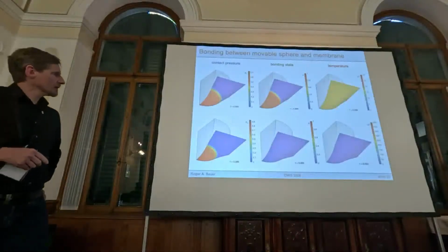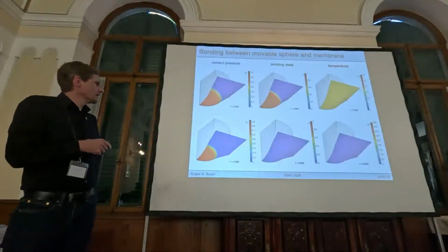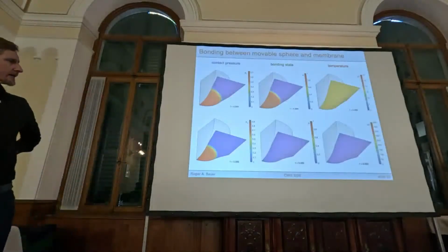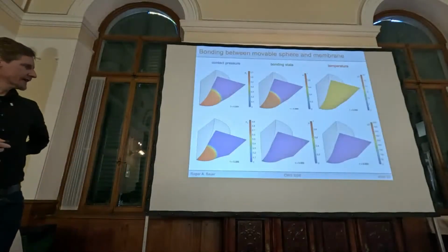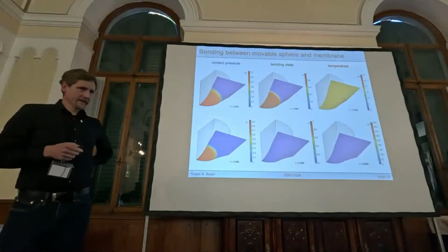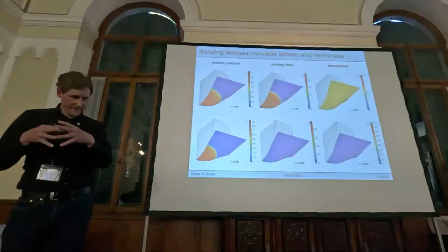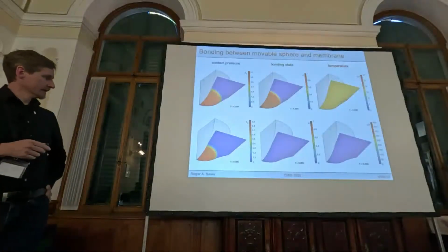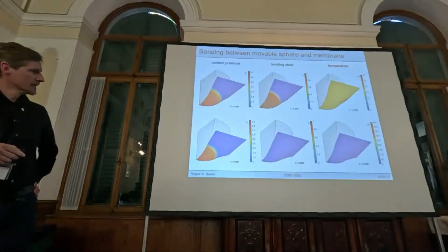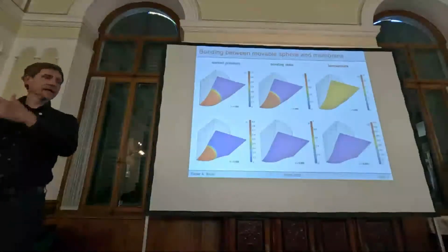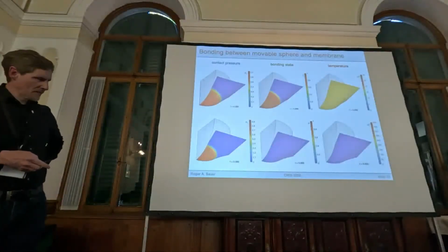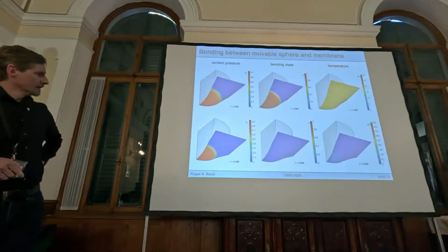As a toy problem, I also looked at the other way around. You can also make the ball come up if you examine the Gough-Joule effect, where the stiffness increases with temperature. That's a known effect in rubber-like materials. If the stiffness goes up, then the deformations will decrease and the ball will have to come up, and this is also something you can see here.